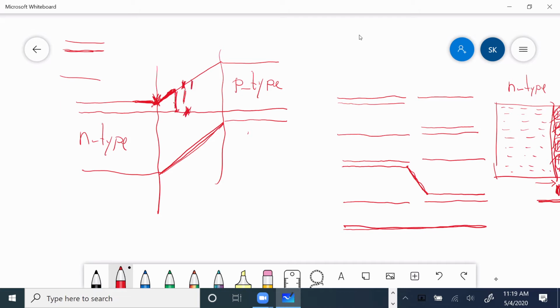At that point, the distance between the Fermi level and the conduction band is the same as the distance between the Fermi level and the valence band. So I'm becoming further away from N-type. Here I become kind of intrinsic, and from then on I become even P-type, because now the Fermi level gets closer and closer to the valence band.